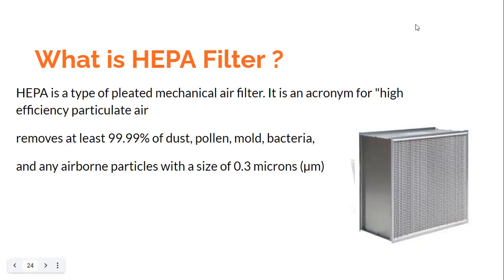But from the filtering media perspective, the level to which it can filter, it is a high efficiency filter, giving you a filtering efficiency between 99.95% to 99.99%. And this, as you see, is used in clean rooms and applications which demand that such smaller size airborne particles are also to be removed. And how small? Remember this number. It is 0.3 microns.